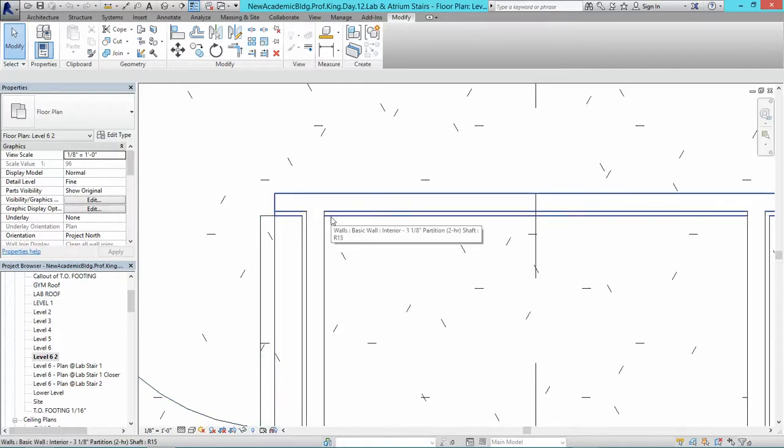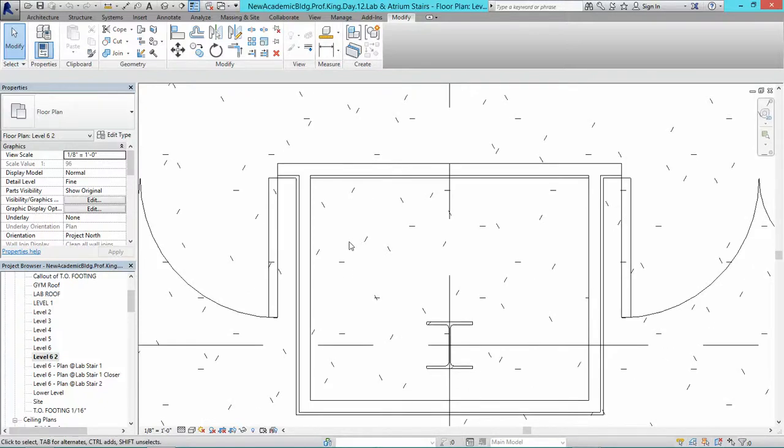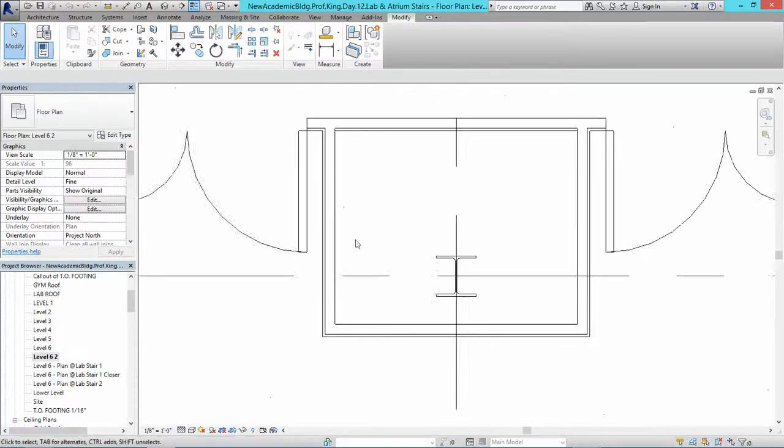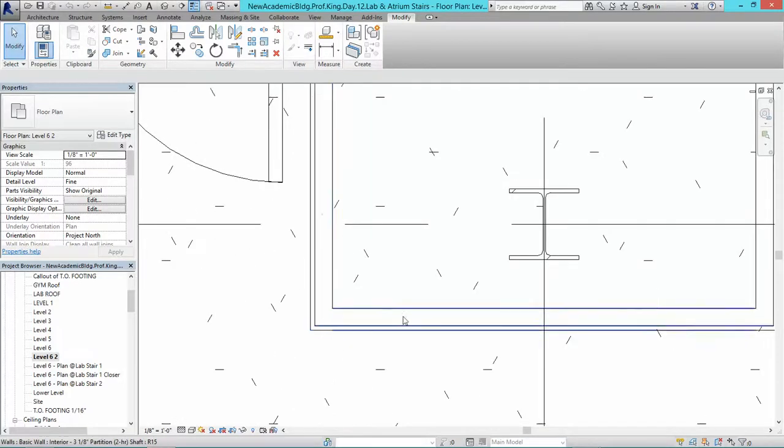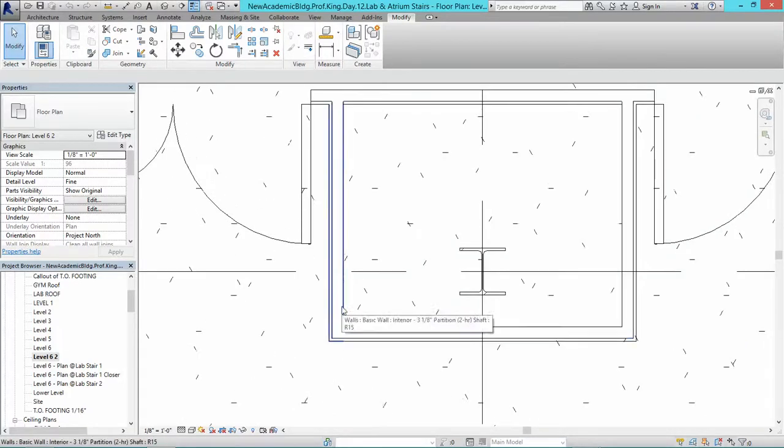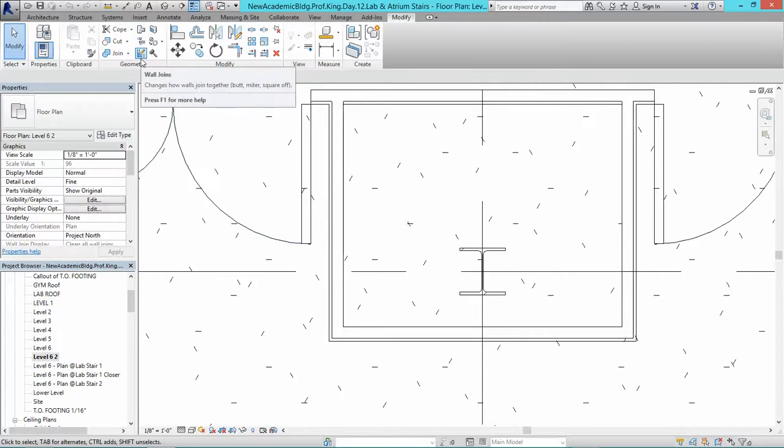So depending on fire rating, depending on layers of sheetrock in one side versus how many there are in each side of that one, if it's a shaft wall or if it isn't. So that meeting point is different in different scenarios. Also the meeting point in the corner point is often different for different scenarios.